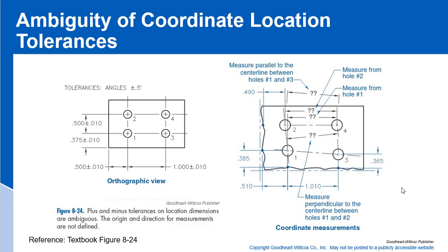But if you look at this, I'm not taking that measurement relative to a coordinate frame. There's no datum coordinate frame that I'm measuring to. I'm measuring from this one location here. And as illustrated in this cartoon, you can see that maybe it's not the exact position. So how do I really know where I'm at? And when I start checking between hole to hole, I use my calipers to check from here to here, and add a diameter to try to get this hole location. But how do I know I'm really squared to the datum reference frame?